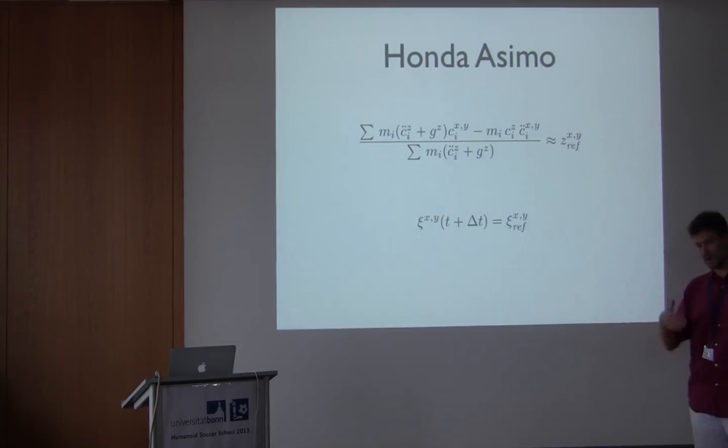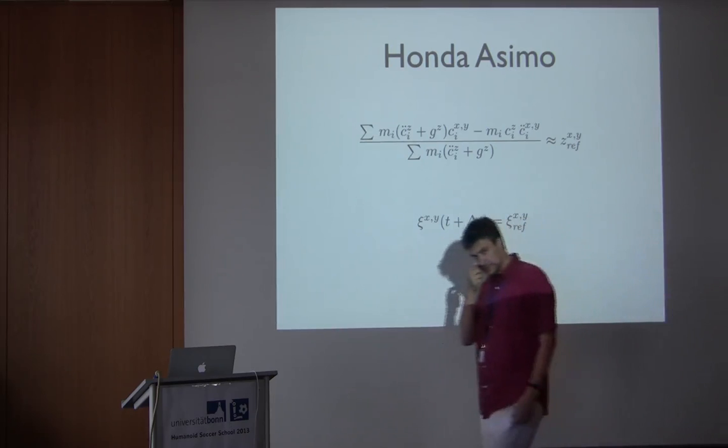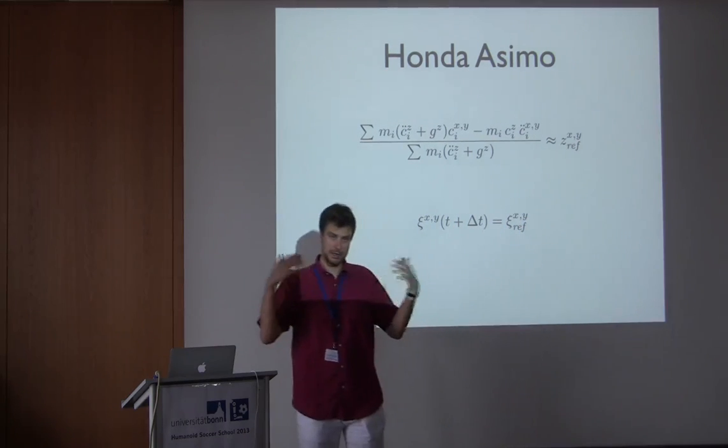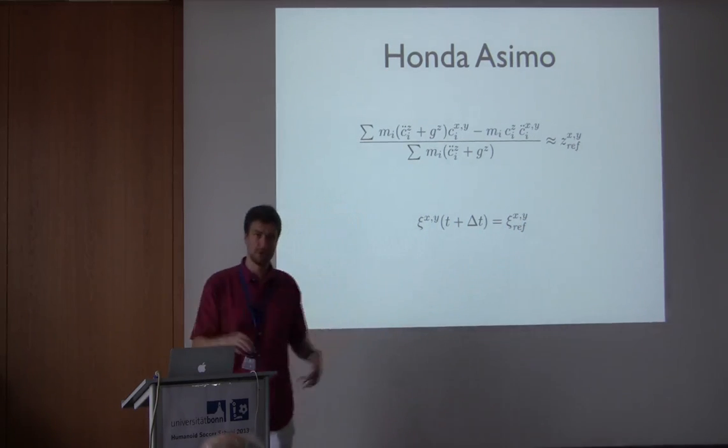And people now are combining this with hand grasping, so that you can take into account the grasping force and maybe the compliance directly in your MPC for the balance, so you can then anticipate your manipulation task in your balance and things like that. So these numerical schemes can be expanded to more general cases.